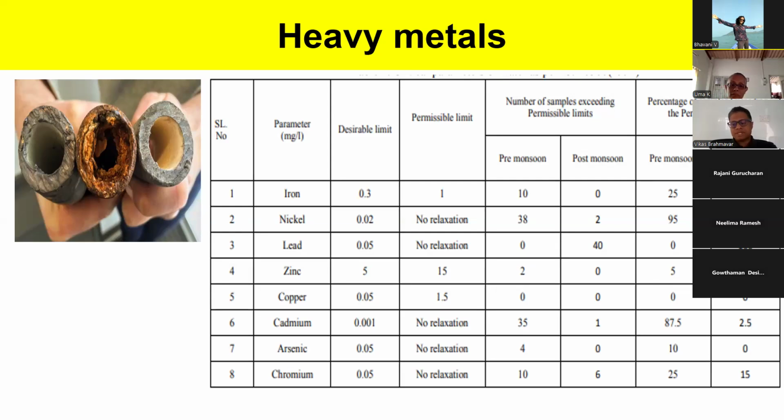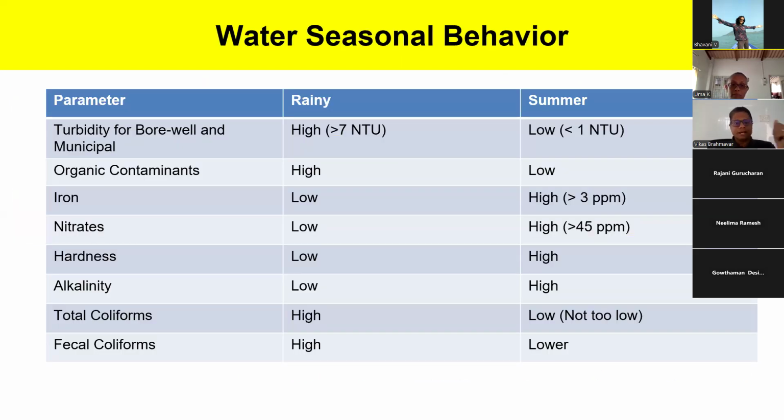The reason why we always say testing once in 6 months is that pre-monsoon and post-monsoon, we see a significant difference. And year on year, there is significant difference based on the gradient, on where the surface water is flowing, where the sewage lines are changed. The quality drastically changes. In Jagdish Nagar, we have noticed changes where organic contamination was not there at all, and just after a few rains, there is severe organic contamination and all the filters start choking. They buy borewell water or tanker water, or they have their own. There's a severe change in the quality of water.